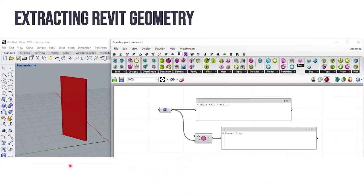All right, and then we can see that reflected in our Rhino interface there. So similar to other Grasshopper geometric components, output geometry is shown as a preview in both Revit and Rhino viewports. So very basic example, but as you've seen, working with Rhino inside Revit is very intuitive and somewhat simple. Well, I say somewhat because it's still programming, so you still got to know what you're doing, but it's very intuitive and pretty straightforward.